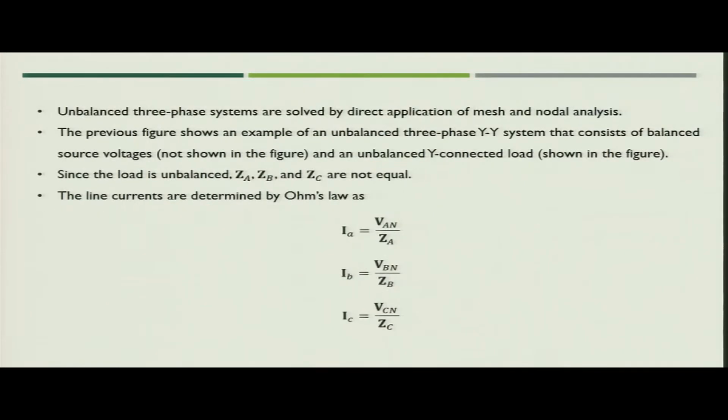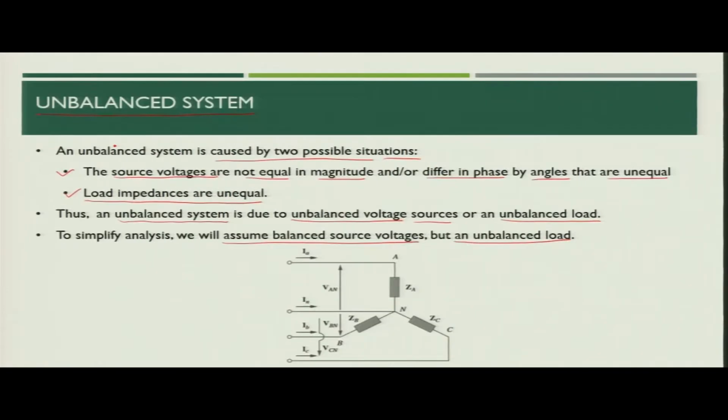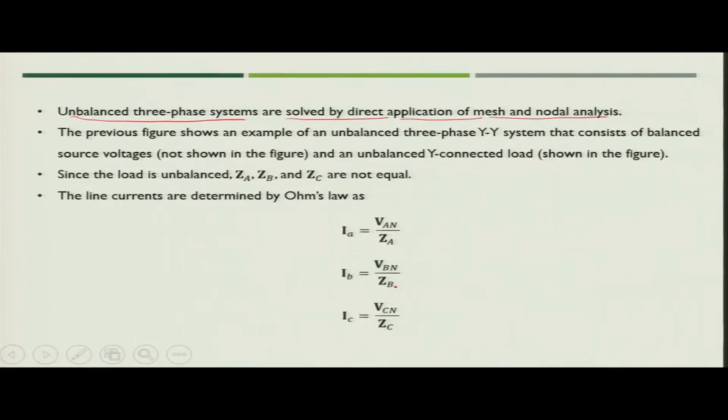In that case, for the unbalanced 3-phase system, the various electrical parameters can be calculated by direct application of either mesh or nodal analysis. The figure in this slide is an example of an unbalanced 3-phase star-star, or Y, system that consists of a balanced source.